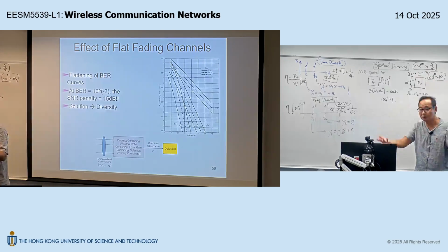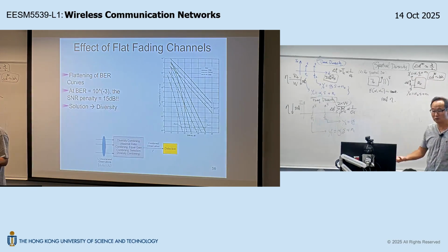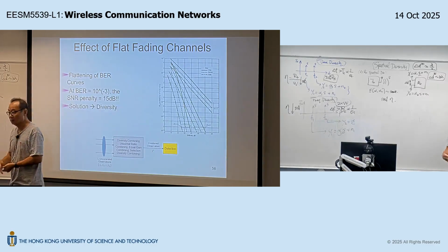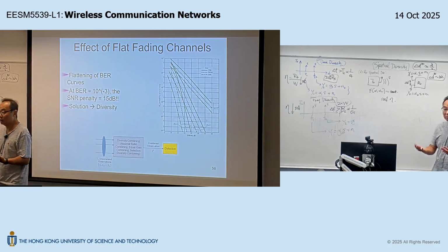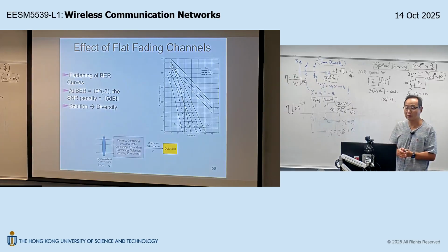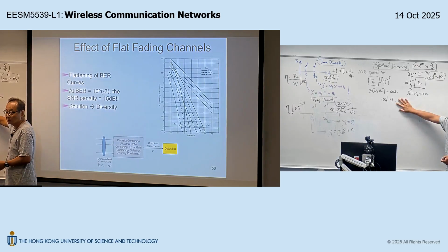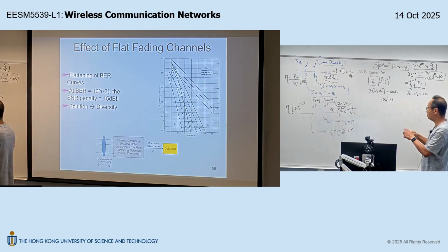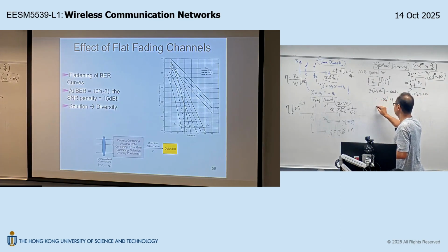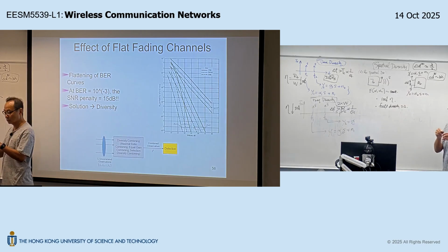If you have 4 ears, you will get extra benefit from having this 4-order diversity. But as a transmitter, I don't need to worry about how many ears you have. You understand the scenario? Because of that, there's no penalty on the spectral efficiency. You have 100% throughput and full diversity, in this case, two-order diversity.